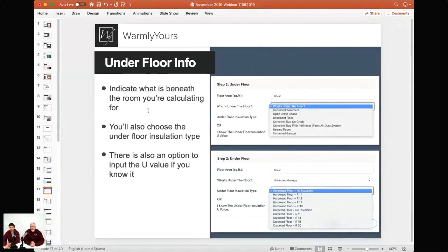Yeah. So step 2, as soon as you've put in all the information in step 1, go to step 2. Something I want to add right away here is, if you don't have some piece of information, like in this particular example, maybe you don't have the insulation type R value, try to pick at least some realistic or maybe even worst case scenario number, because that way the system will generate a heat loss based on that worst case scenario for the underfloor insulation type.